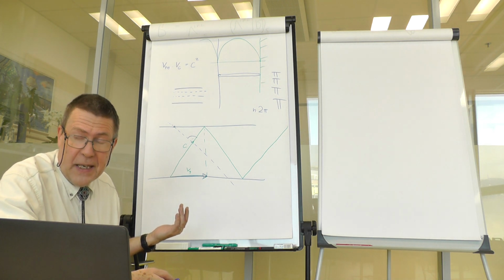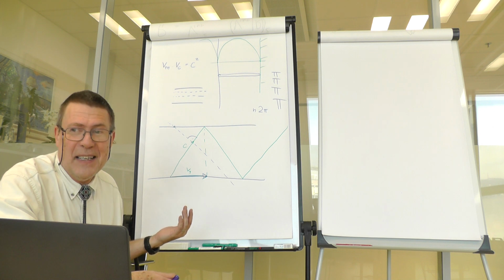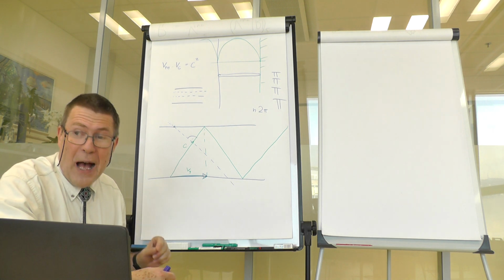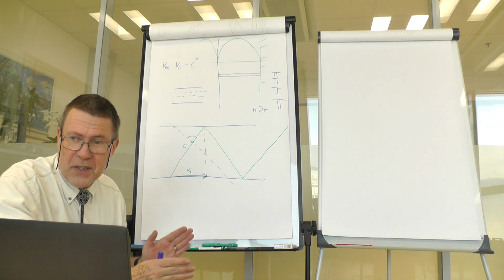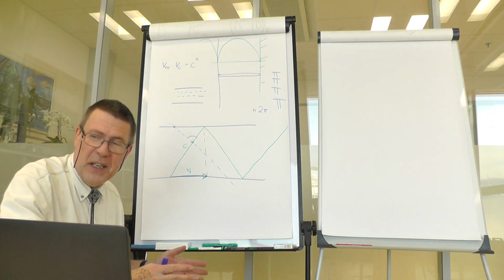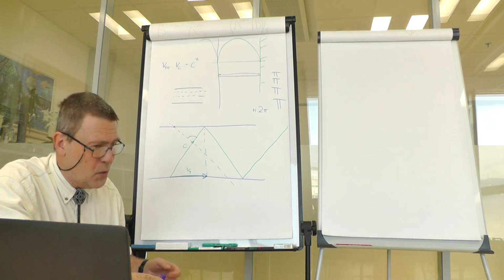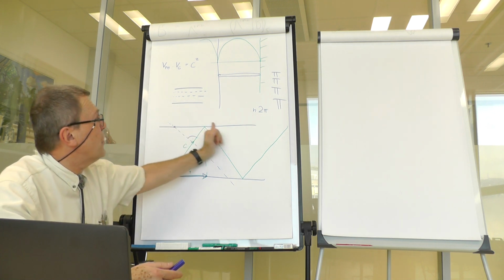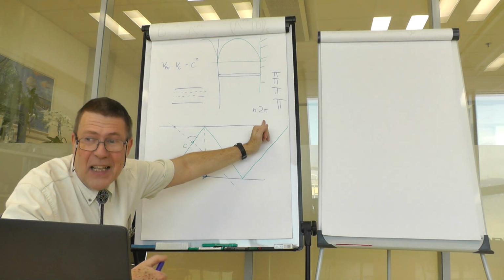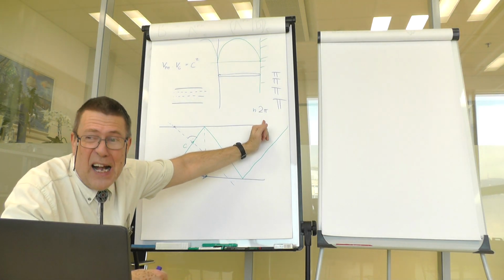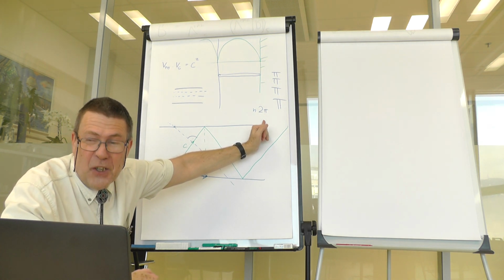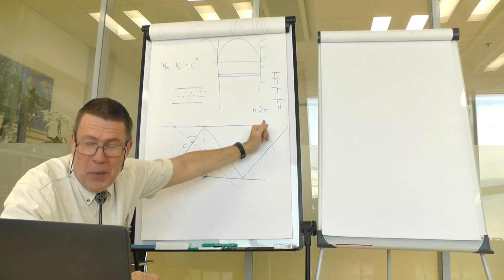Well, because it's sometimes quite important, especially in impedance matching, which we will talk about later, to have a transmission line of a certain phase length, say 25 degrees, 78 degrees, 220 degrees. But this refers to a portion of the wavelength, and the wavelength is defined as the distance of 2 points on the line that differ by 2 pi in phase.